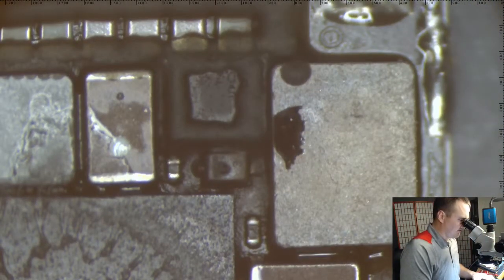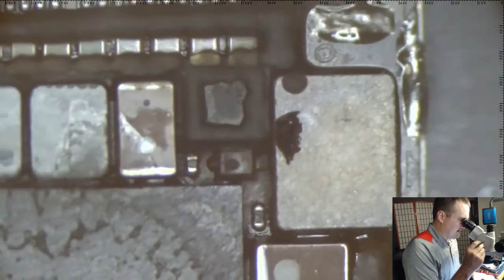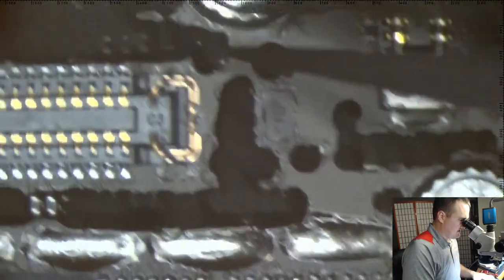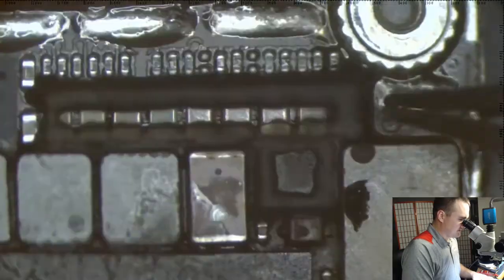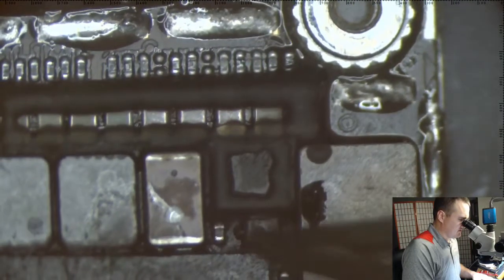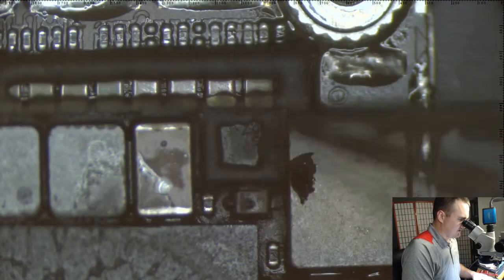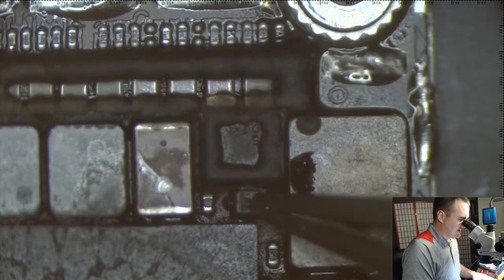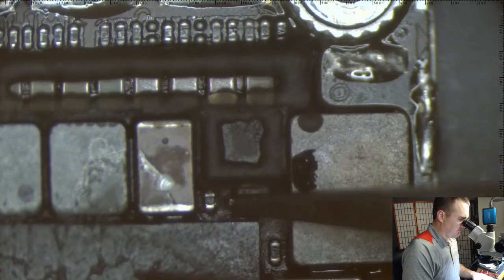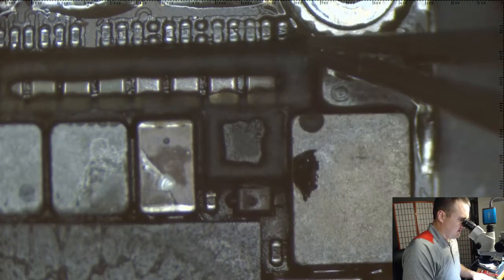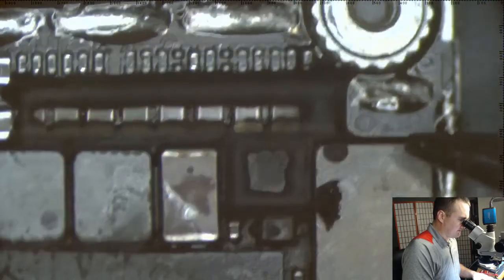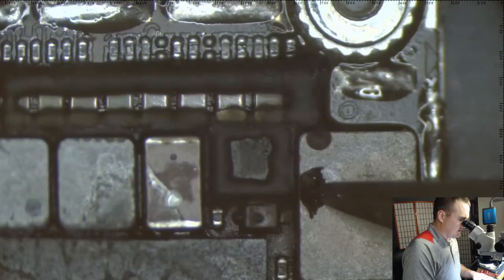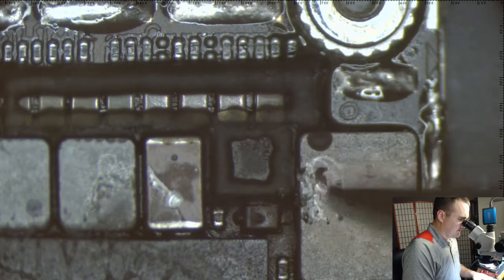So on here we can see a couple of very clear indicators of what happened. If you're familiar with this repair, you will have seen exactly what the problem is also. Here's your boost driver, here's the coil, here's the diode, here's the 100 pF capacitor. Here are your 2 VCC main capacitors. Here are your 3 backlight anode capacitors.